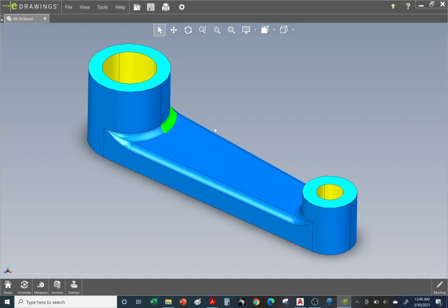So if you look at the old vehicles, not so familiar with the newer ones, but if you see the water pump, you'll see that like in an old Chevy or old Ford, they'll have a rough texture to it because it's cheaper to cast it into a mold. Take it out. Once it's solid, it'll have the rough surface. And then you can come in and machine off the surface. So you have a nice, flat, planar surface.